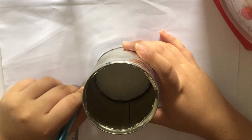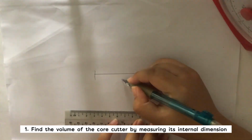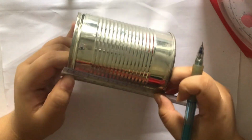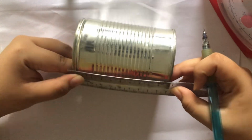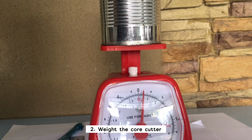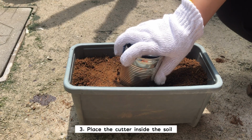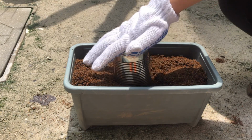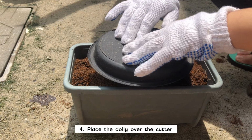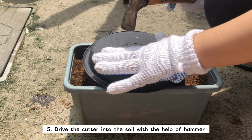For the field density test, I use the core cutter method. So first, find the volume of the core cutter by measuring its internal dimensions using the formula V = πd²h/4. Next, weigh the core cutter and place the cutter inside the soil. Next, place the dolly over the cutter and drive the cutter into the soil with the help of a hammer.